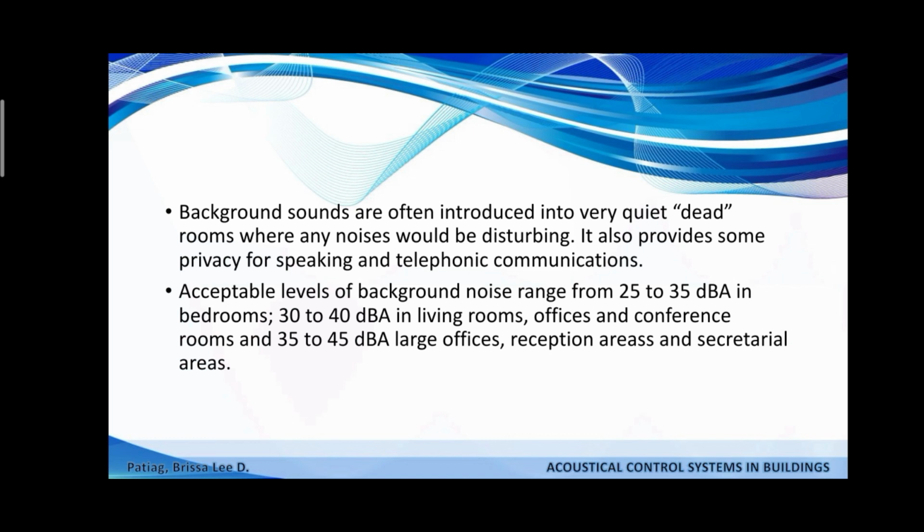Acceptable levels of background noise range from 25 to 35 dBA in bedrooms. So, these are the ranges of background noise. And in living rooms, the background noise ranges only from 30 to 40 decibels.